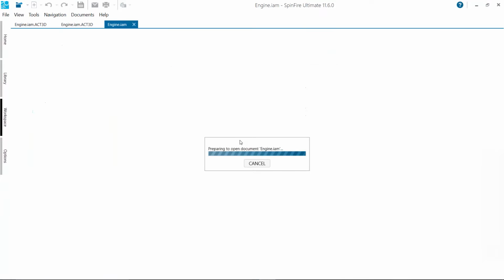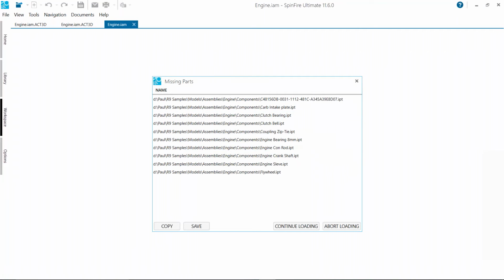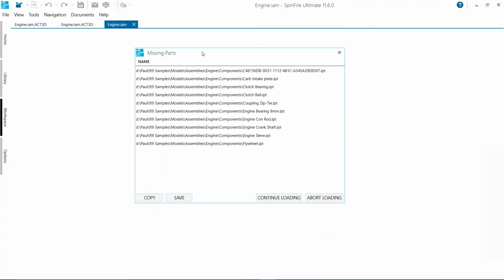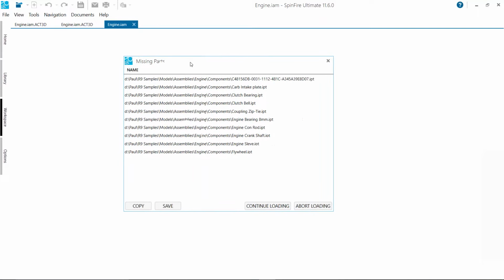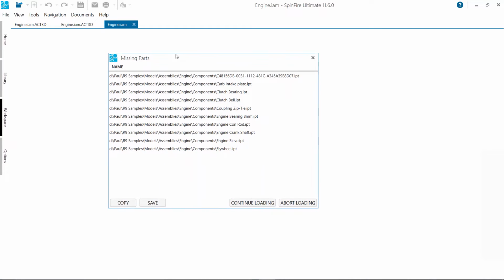There it is. So you're going to see a message here checking for parts or missing parts. I hope. There we go, checking for missing parts. So right here, if you ever get an assembly from a customer and you think it doesn't look complete, you don't have to email me that something's missing. Turn on check for missing components, because that happens a lot.